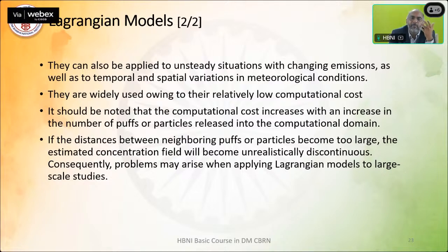Okay, so that's part and parcel of any modeling you do, where you do a sensitivity study, to see which node size works and which node size doesn't work. By sensitivity study, we mean you do a nodal sensitivity study, where, when you ask how you choose node sizes, you have to do analysis and see that there is no further change in the quality of results.